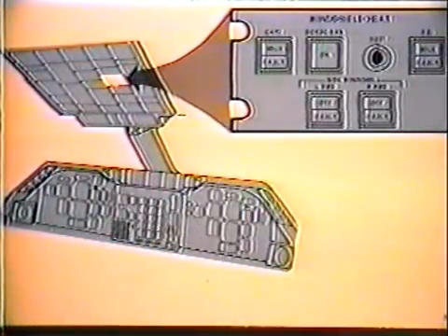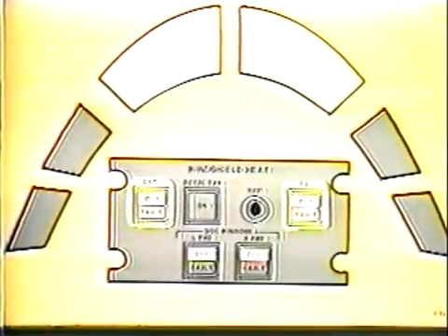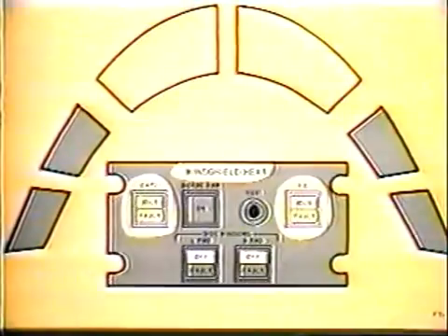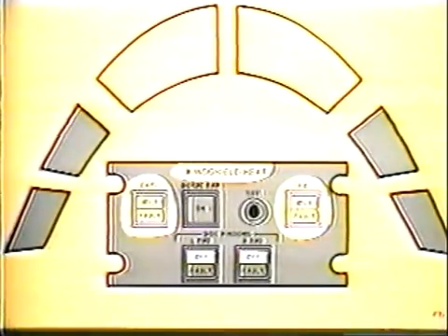Windshield heat and defog. The windshield heat control panel is located on the pilot's overhead panel. With the captain's or first officer's windshield heat switch unlatched, the idle legend is illuminated. Low temperature heat is being applied to the captain's and first officer's windshield. High heat is applied to the captain's and first officer's forward windshield when the switches are latched and dark.